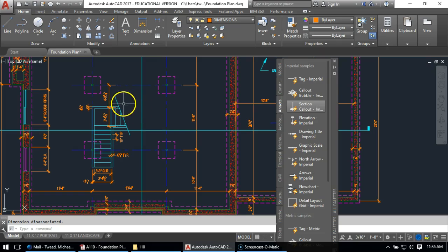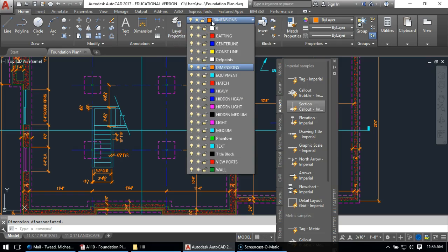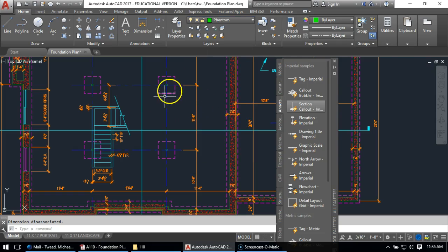I just noticed there's a set of lines which we don't have the dimensions of, and we won't be able to put in unless we have the first floor plan to show where the stairs start. So I'm just going to estimate it for now. Maybe we'll come back and fix it later. I'm going to change my line and go to, let's see, maybe Phantom. We'll see what this line weight looks like.